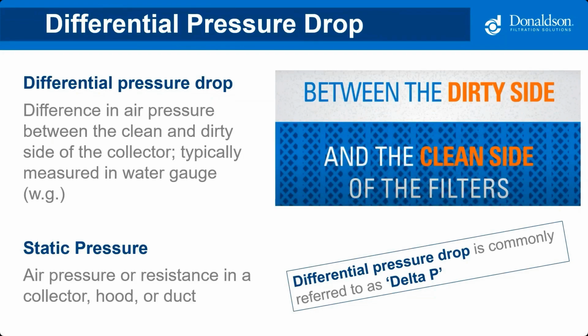The difference in that pressure is called the differential pressure, and it's typically measured in water gauge, or inches of water. The reason this is so important is that I always call it the doctor's stethoscope, right? He grabs it, throws it on your chest, a couple deep breaths, you get lightheaded, etc. But it really helps to tell, real simply, what's going on inside the dust collector. So that's going to be one of the very first things I always ask: what's your differential pressure drop? Because it's just that important.